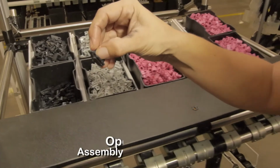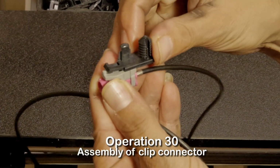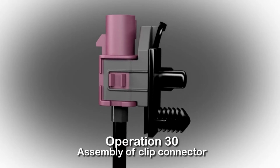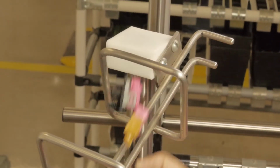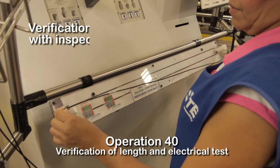Operation 30 includes assembling of the clip connector to the lock that was assembled at Station 10. Care should be taken to fully slide the connector and assure it is fully seated to the lock. Operation 40 includes checking the length of the cable and the electrical test.